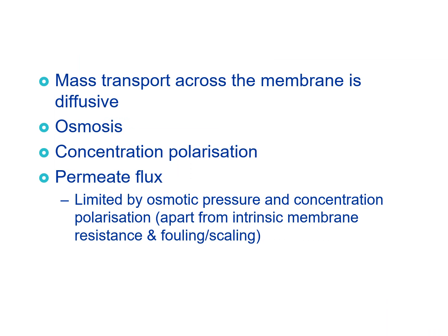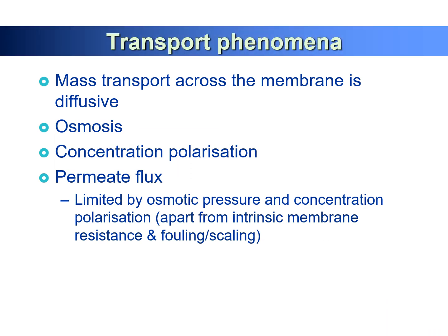So now, the transport phenomenon of the reverse osmosis membrane. Mass transport across the membrane is by diffusion, and osmosis is very important, so we need to better understand osmosis, concentration polarization, and permeate flux, which is limited by osmotic pressure and concentration polarization, apart from the intrinsic membrane resistance.